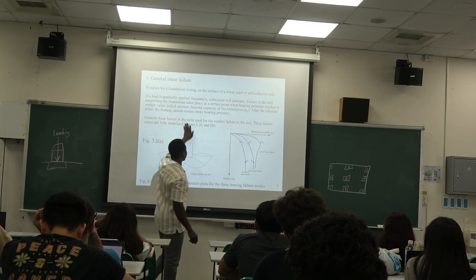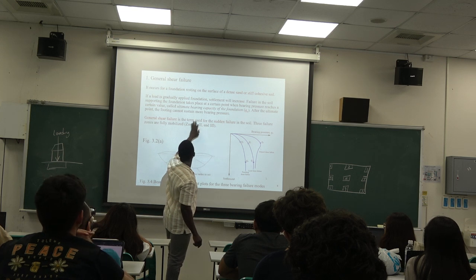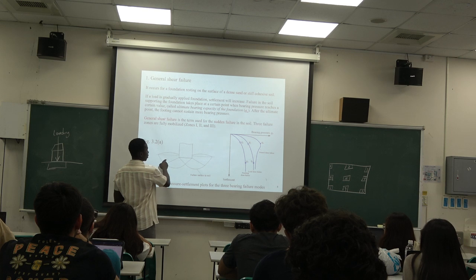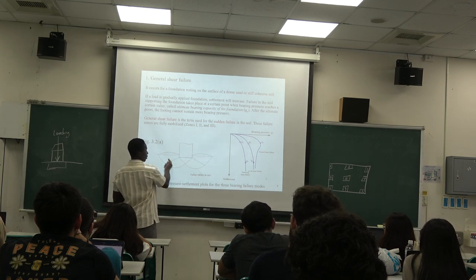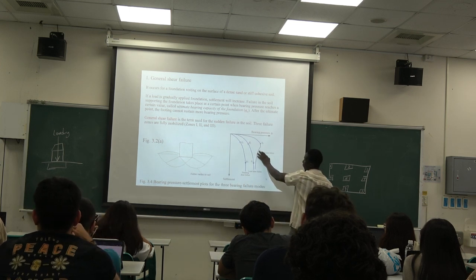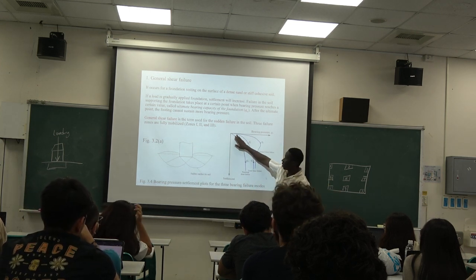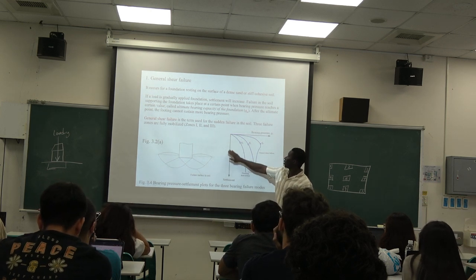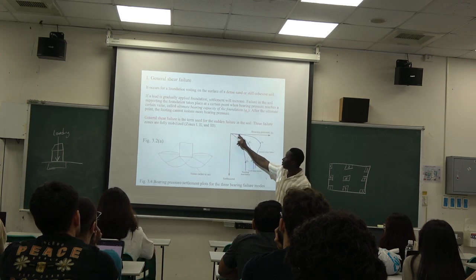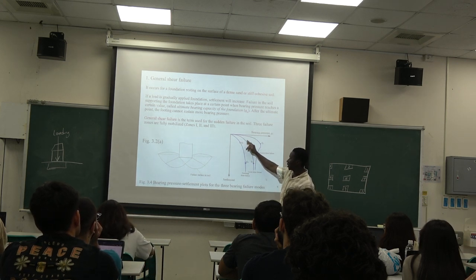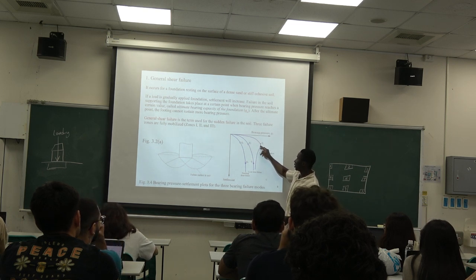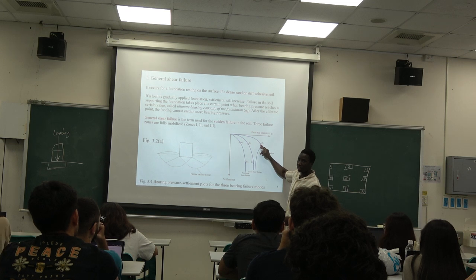Okay, general shear failure is the term used for the sudden failure in soil. The three mobilized zones, so we already talked about this: zone 1, zone 2, and zone 3. Down, out, up. Okay, and here we have a diagram for the general shear failure. So this is the settlement you will experience, and this is the bearing pressure, right? You apply the loading, the bearing pressure keeps increasing, you have more settlement. You have more settlement, then you reach here, the ultimate point.